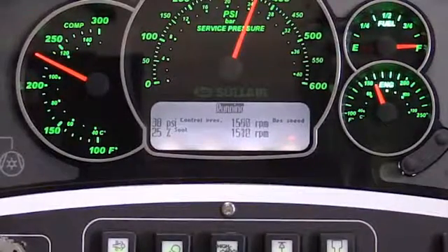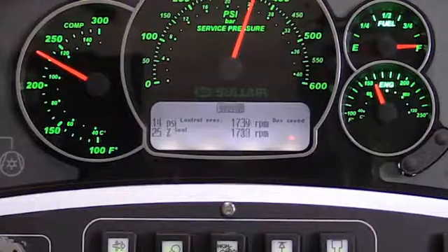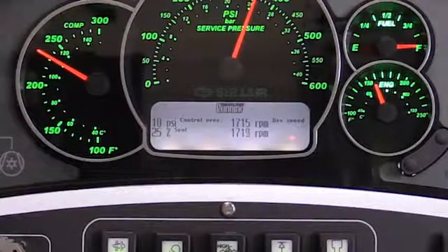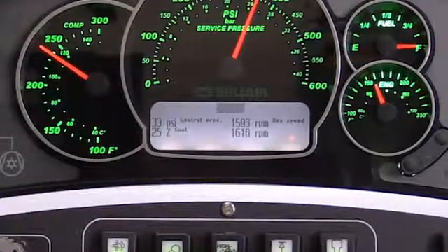This is right in the middle of the modulation zone. In other words, the machine's about half capacity. Displayed now is about mid-modulation. You'll notice that the control pressure is about 30 psi. This puts us right at about half capacity of the machine.